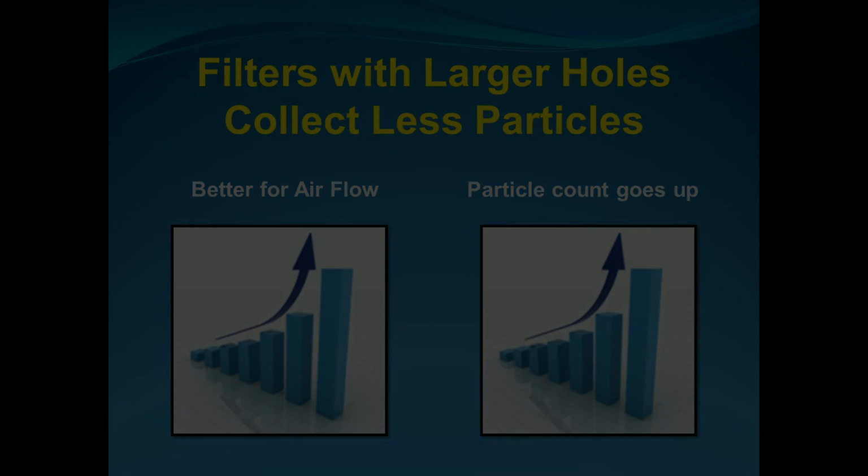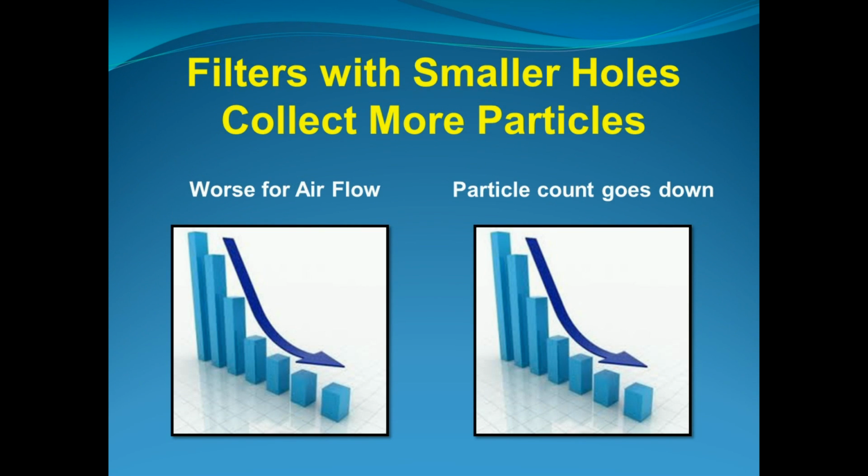So there are some benefits to the good airflow, but the negatives outweigh the positives by allowing all that dirt to cover our equipment and causing premature breakdowns and inefficiencies. On the other end of the spectrum, we have filters that have much smaller holes, so they're going to collect more particles, but now they have bad airflow, though the particle count will come down. You're going to have less of the heavy particles in the air.